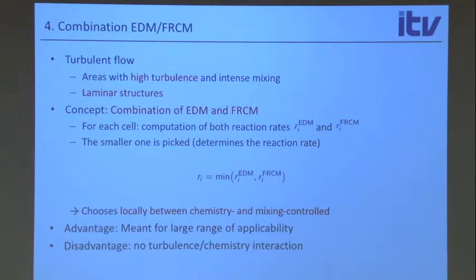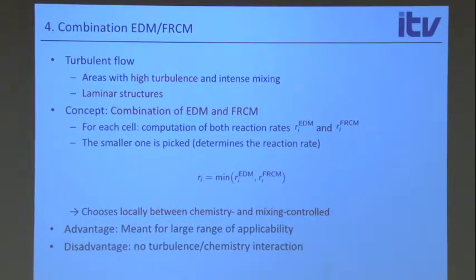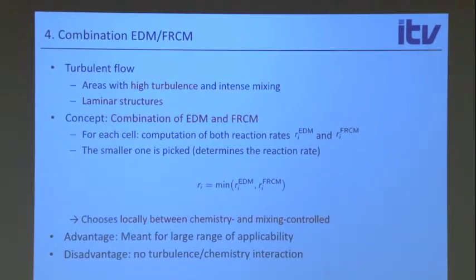not really blend. This here, by the way, I understand, because this says I have one asymptotic limit, which is finite-rate chemistry, where I don't need closure. It's very slow chemistry. And I have the other asymptotic limit, very, very fast chemistry. And I have a model that's formulated for both these assumptions, one for each of these assumptions. And now I just try to blend these together. That's something I understand. I can really understand.